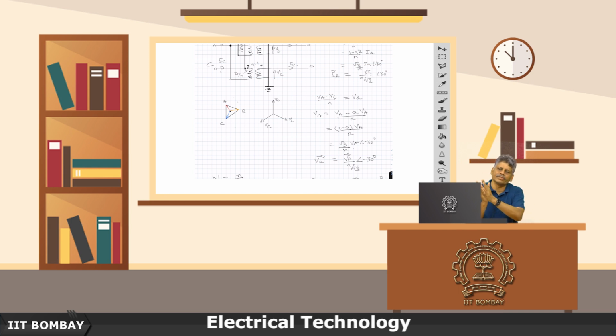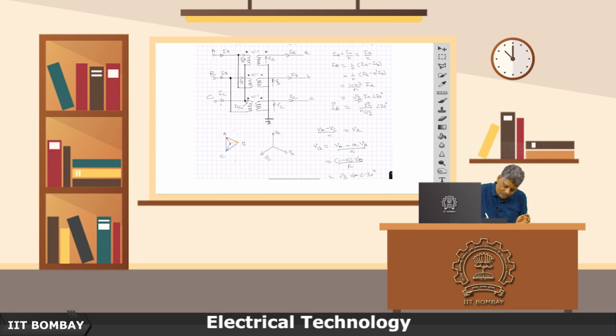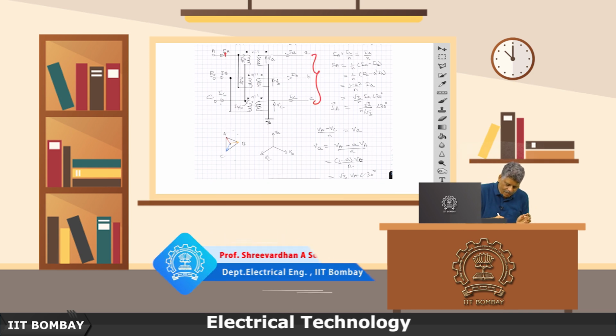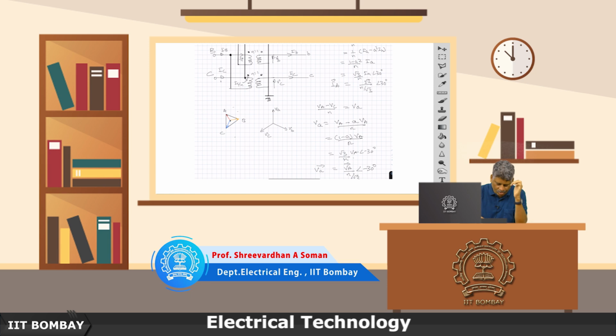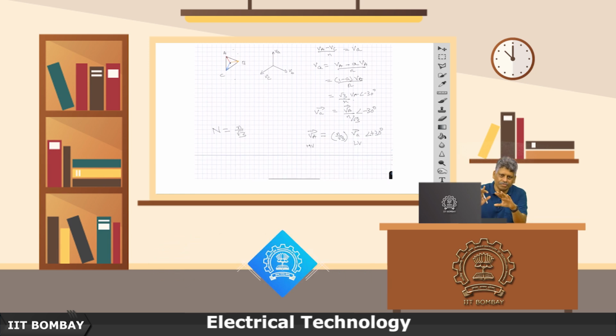The consequence of this is that when the voltage goes by 30 degrees and the current also goes by 30 degrees in the same direction, then the power factor which is seen on this side and the power factor which is seen on the other side also remains the same. So, this covers these two important 30 degree phase shift concepts. We will take up some examples afterwards.